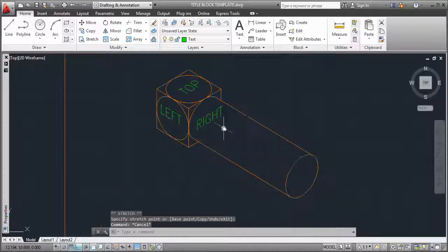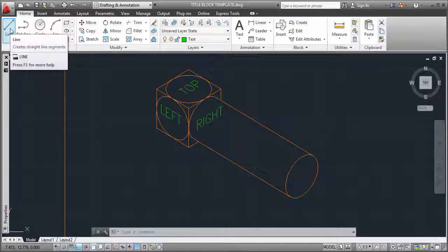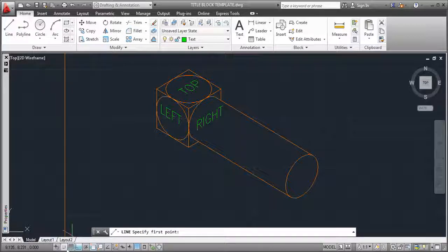Now if you look at the piping, all it pretty much is lines and also boxes and cylinders, so you should have all the information you need. As you're doing the valves, just to give you a little bit of help, if you go ahead and click the line command, you have your ortho on. Find the plane that you would like to use, F5. So I'm going to do a valve on the top plane.